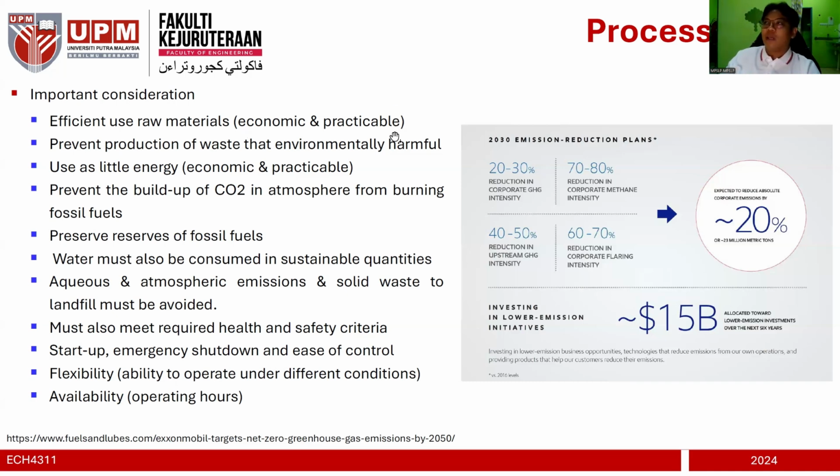Okay, why is this? It's because you cannot just simply achieve 100% conversion. For example, in ammonia production, right? Because it's an equilibrium-based process, you can just simply raise the pressure up to 800 bar. But was it worth it? Probably not, because your wall's going to be thick or something like that. And you can also increase the temperature, but then you probably need to figure out a different material for your reactor, something like that.